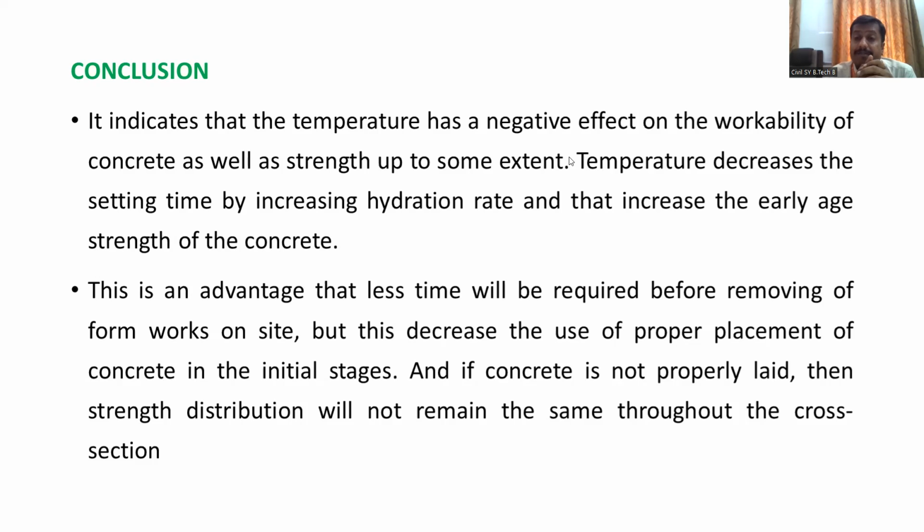So in the night, definitely there is a drop in the temperature. Maybe the temperature ranges from 20 to 27 degrees centigrade, maybe lower than that. So that is the best time for us. We can place our fresh concrete.